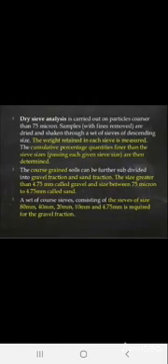Going ahead, the dry sieve analysis is carried out on the particles coarser than 75 micron. Samples are dried and shaken through a set of sieves of descending size. The weight retained on each sieve is measured. The cumulative percentage quantities finer than each sieve size are then determined. As I told you, a number of sieves are put in descending order, and we have to sieve dry soil. How do we dry the soil? We put it into the oven for 24 hours. Then after that we perform the sieve analysis or any type of test, right?